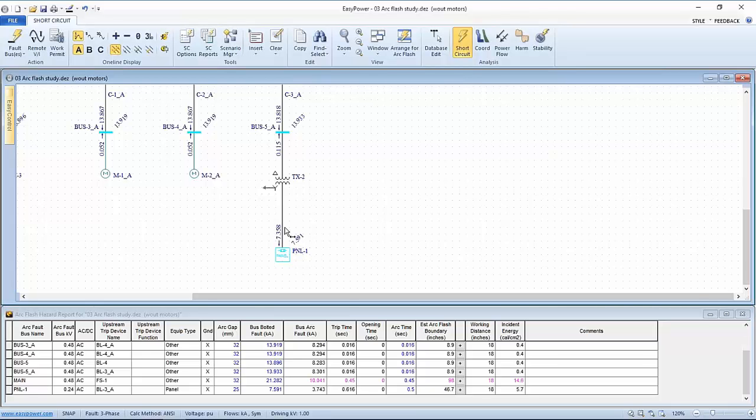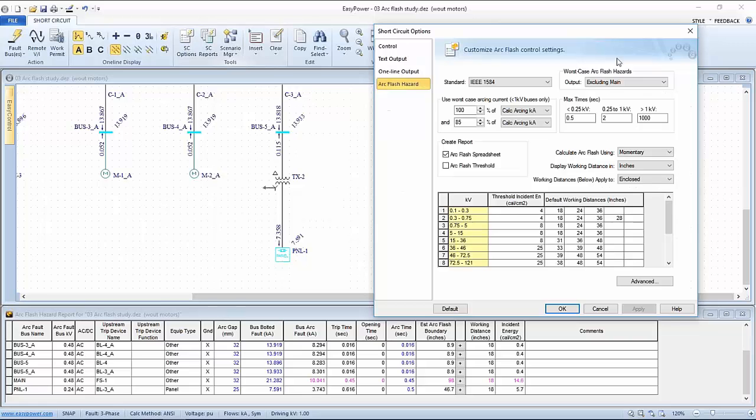I can take steps, and that would be my preferred procedure, rather than shortchange the calculations being made here, to make some provision to move this protective device outside the panel so that when I go to my calculations and look at my short circuit options, I can actually include the protective device.